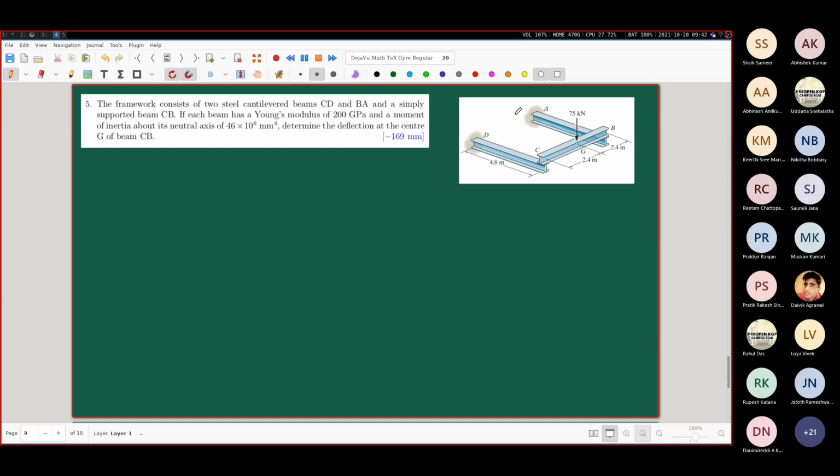So we can consider this case as the sum of 2 cases, like the beam BC is deflected being supported by 2 ends, and we can also then add the deflection due to those cantilever beams. Very good. That is the correct thinking procedure, without even thinking about equations.